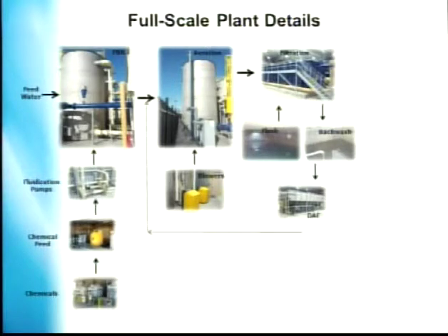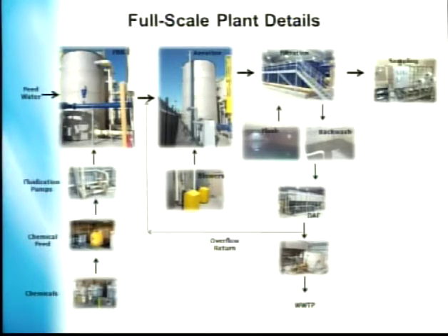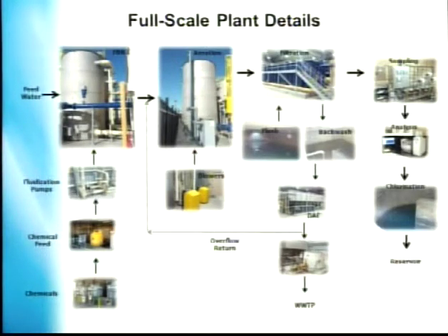After the DAF, the solids are pulled out and the water goes back. It no longer has nitrate in it, so it can go back after the FBR. It doesn't need to be retreated. That goes to a solids tank. The solids go to a small tank that are fed directly to the wastewater treatment plant with the City of Rialto, a POTW, that take that and add it to their aeration basins, essentially. And then there's some online sampling that we do. Finally, chlorination, and then out to the reservoir.